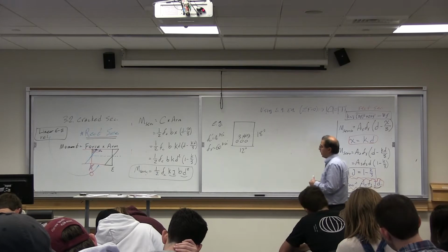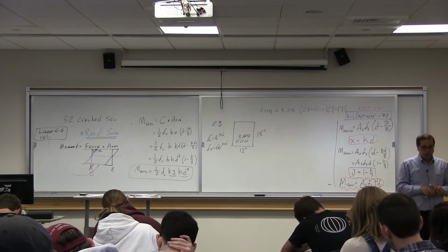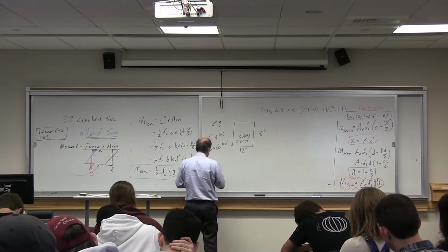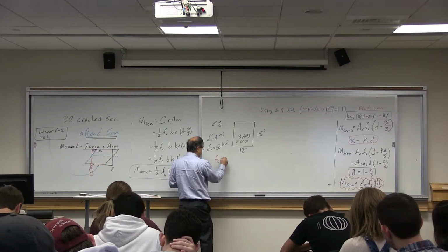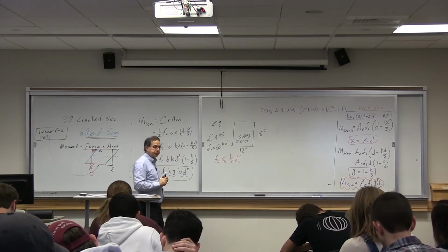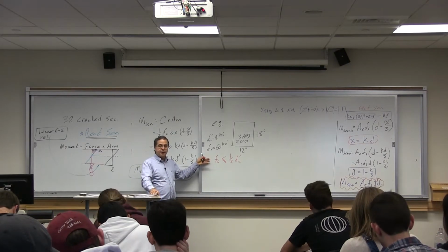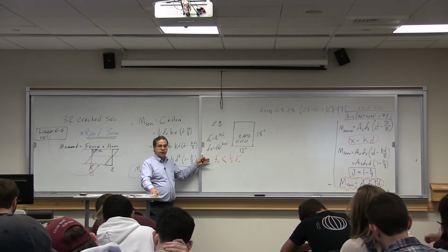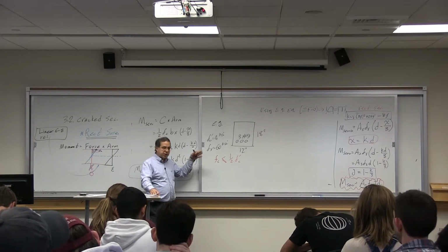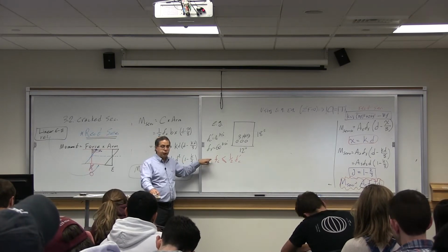F prime C 4 ksi, Fy 60 ksi, 12 by 18, 3 number 9. What we want to solve is this. We want to have Fc less than or equal to 1/2 of F prime C. Why do we want to put a limit like this? What would happen if we do this?